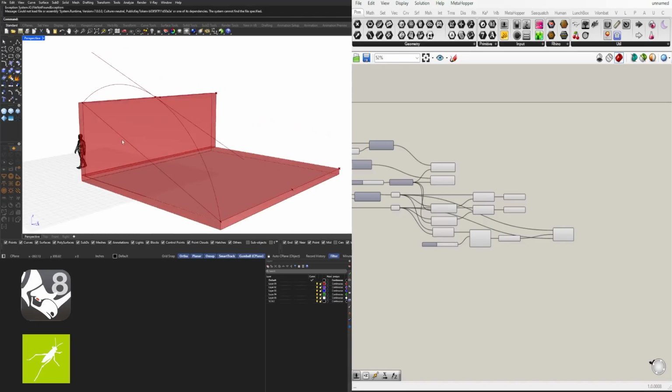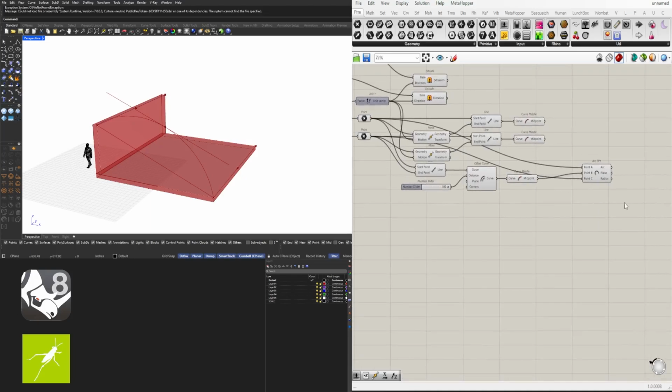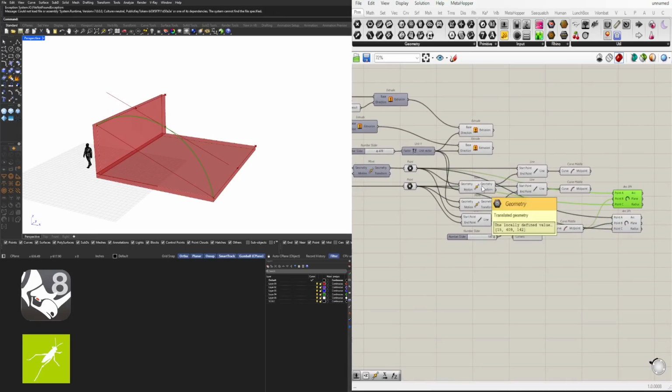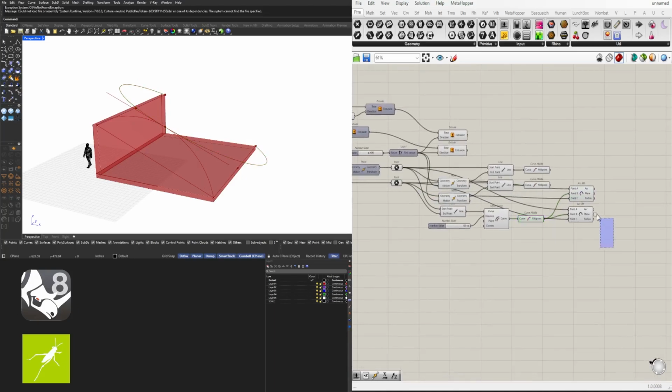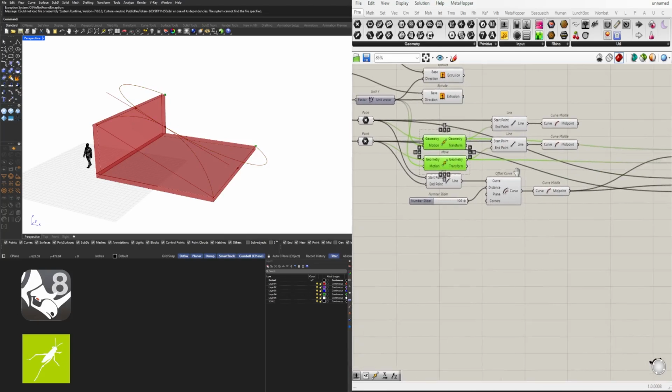Now we need to do the same thing to the endpoint. So what I'll do is create a copy of this arc, use this one as the start point, which is the end one here, and this one that we moved all the way to the end as the end point. Now we need to first create a line segment between the two.